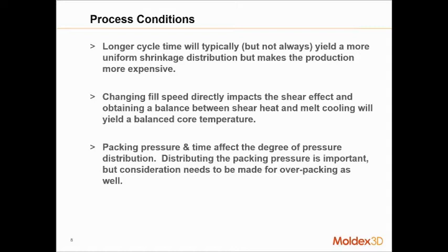And it's very important to differentiate between those two, because our core temperature is not really going to be impacted by our cooling design, and in the same breath, our skin temperature isn't necessarily going to be impacted by what happens in the filling and packing. Now, there is an overlap between the two at some point, but we really want to keep those two effects separated and identify which of the two we're actually trying to impact when it comes to the different types of analyses that we're running.